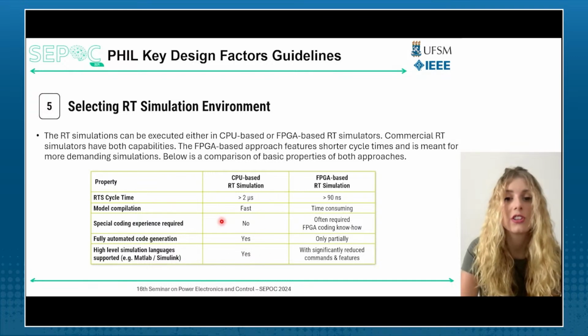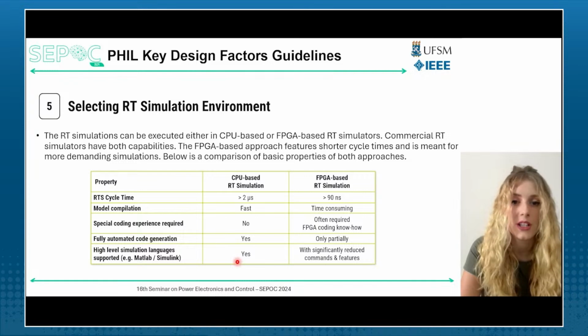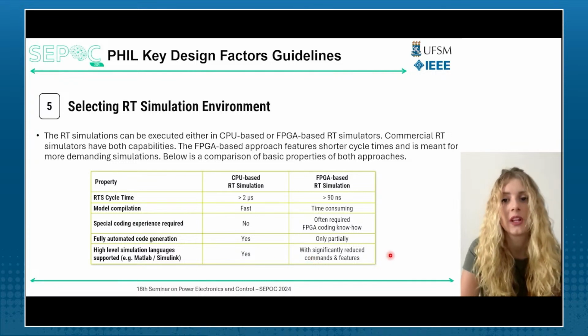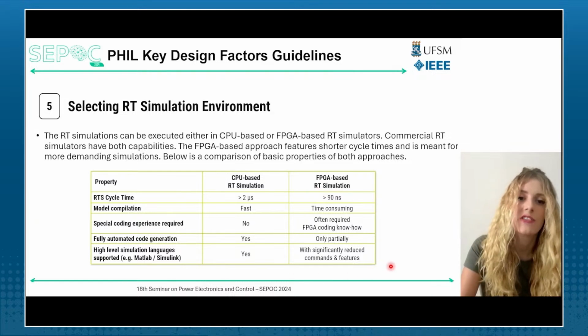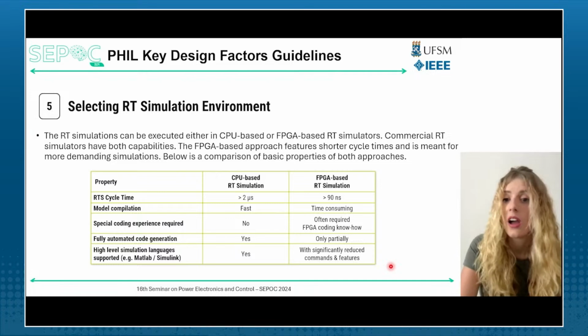You typically do not need to have any coding experience. Code generation is typically automated, and you can use simulation languages like MATLAB. On the other hand, in general, FPGA-based simulators require some coding experience, automation is not so good and you're lacking support, but they are much faster.